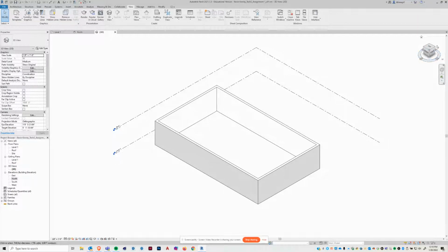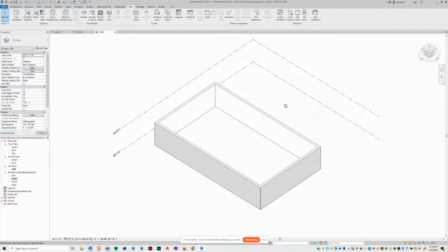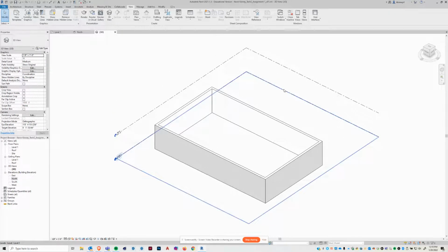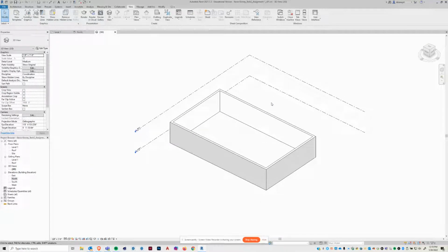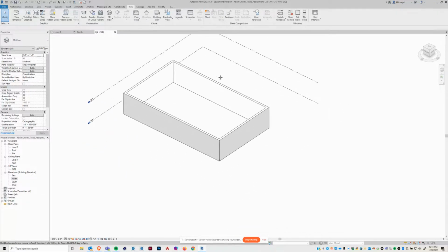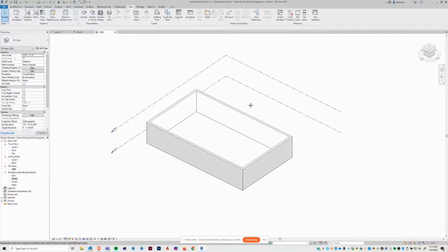So you can use this how you want. I can also hold down Shift and right click, hold down both those and rotate. I can scroll in and out with the scroll wheel, and I can hold down the scroll wheel button to pan. So pan is the scroll wheel button. Orbit is Shift and right click.